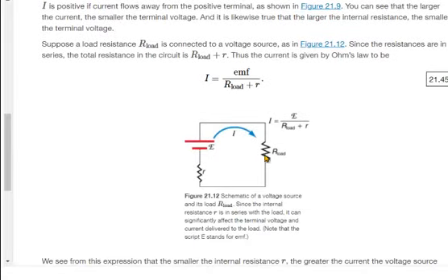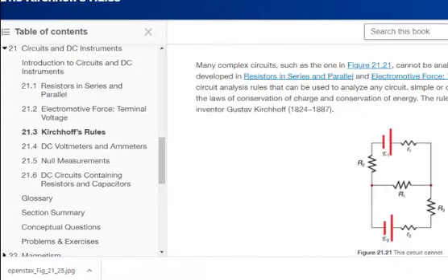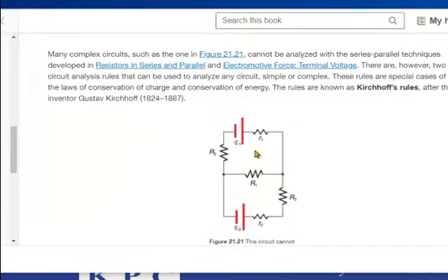So when you have that internal resistance together in series with a normal resistance, which is called the load, then you simply add the two, which is exactly what I'm going to do here. I'm just going to ignore that it's there, but use its value and add it to the resistance.